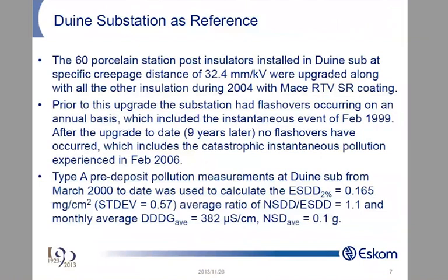Do the stats work? The EU measures with calibrated instruments, so we know. What we do is we take 60 porcelain station posts in a substation. We know their performance, we know their creepage distance, and we know what happened to them during and after the event, the big instantaneous pollution event.